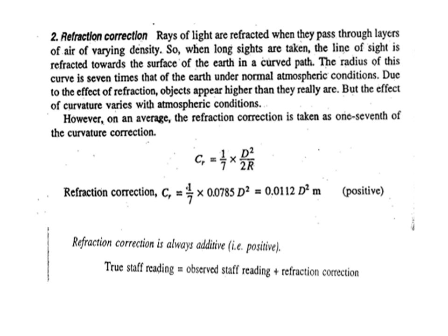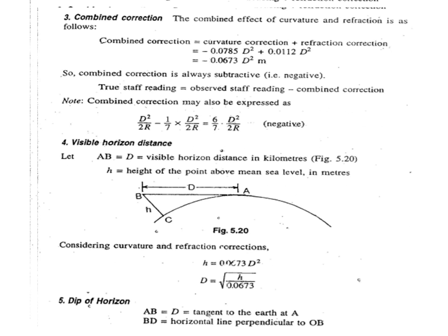Therefore, the error observed on station A equals AA1 minus Aa, that is equal to D tan alpha. Similarly, the true reading equals AA1 minus the error, that is AA1 minus D tan alpha. Similarly, for station B, the true staff reading is Bb, and BB1 is the observed staff reading.